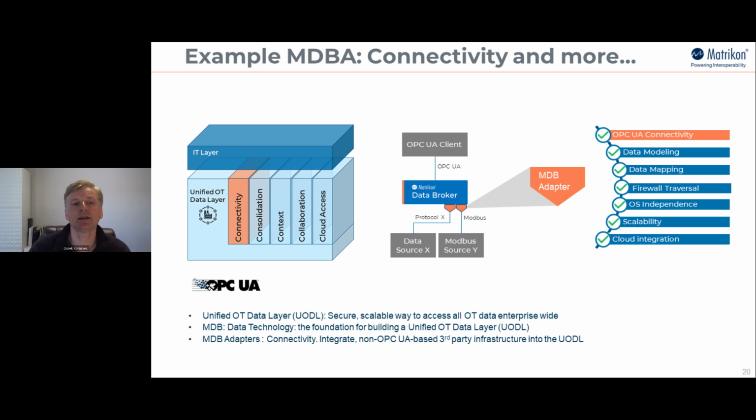Now, the nice thing about using EODL or something that implements it, in this case we call Data Broker, is that it will talk a particular protocol, let's say Modbus, the simplest protocol, and also the most widely used, if you look at how long it's been around and how many applications it has. But it lacks everything from timestamps to engineering units and contextual relationship between the different items. They're just registers, basically.